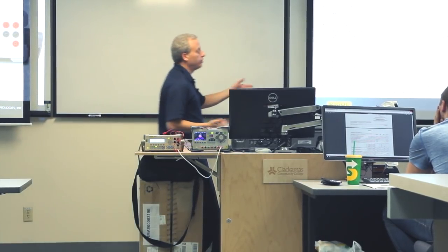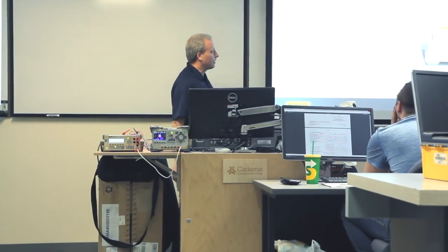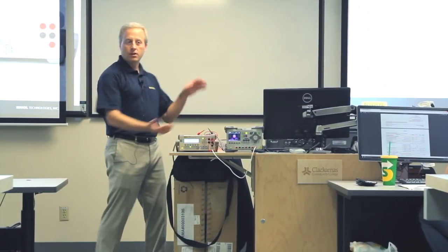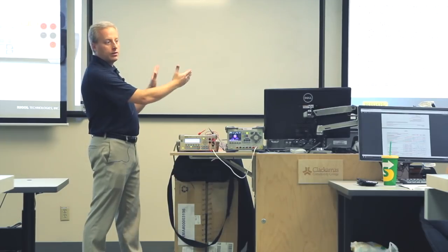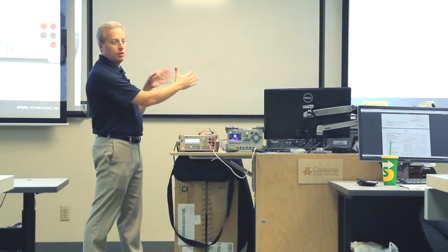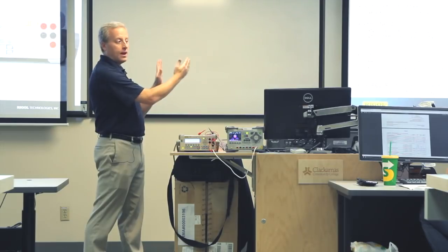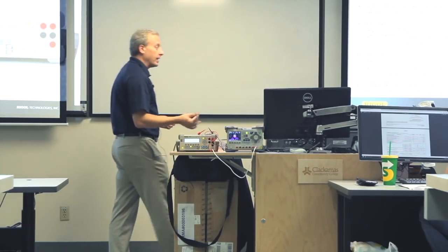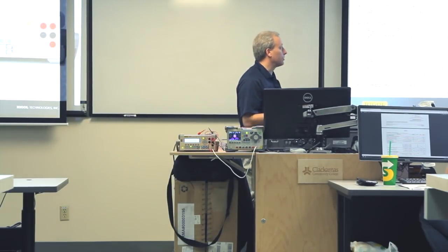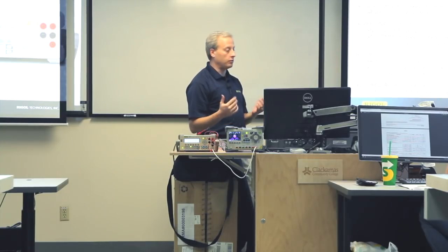So what a DMM does that's special is it can do integration over power line cycles. When you set the instrument to 1 NPLC, what that tells it to do is, in essence, take measurements on the A to D over that 1/60th of a second, 16.67 milliseconds, and then average them out to get rid of the noise that's moving with the power line. So that's one good way to get rid of 60 hertz noise that's fairly common in low-level measurements.